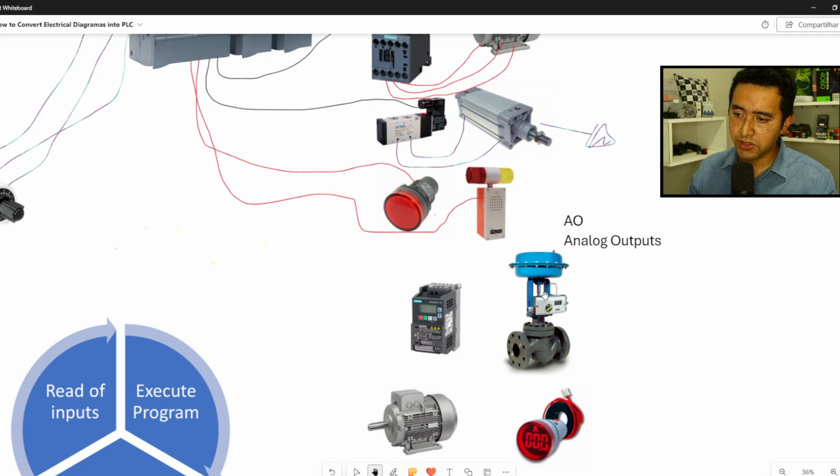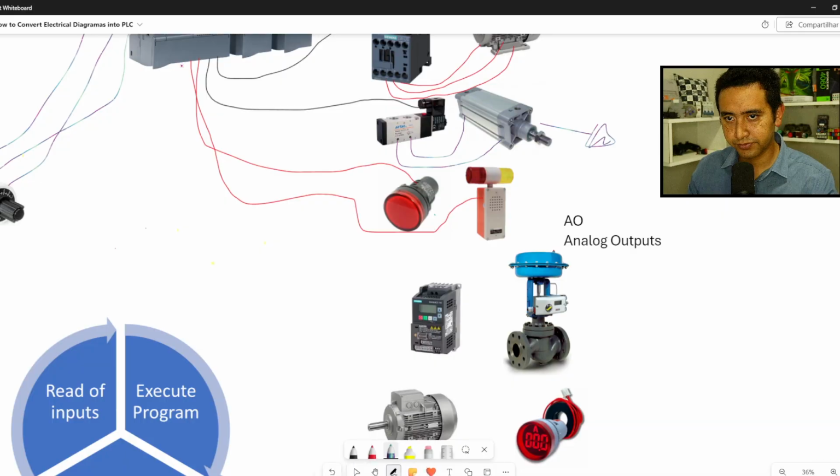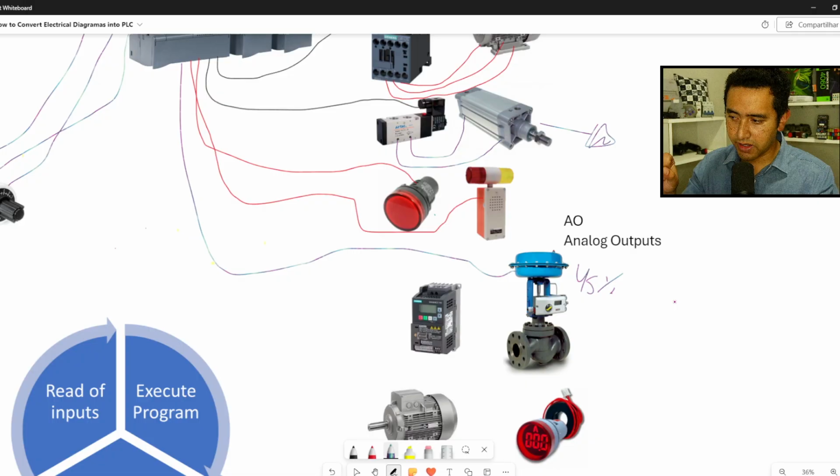Then I need to open a steam control valve to raise my temperature. Then it's possible to put in the valve 45% of openness. Then I open 45% mechanically. Then I put steam in my process.